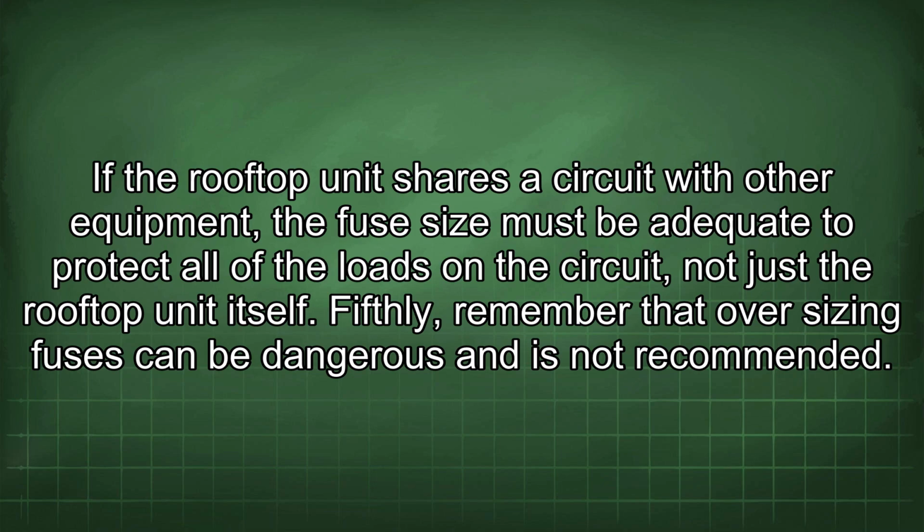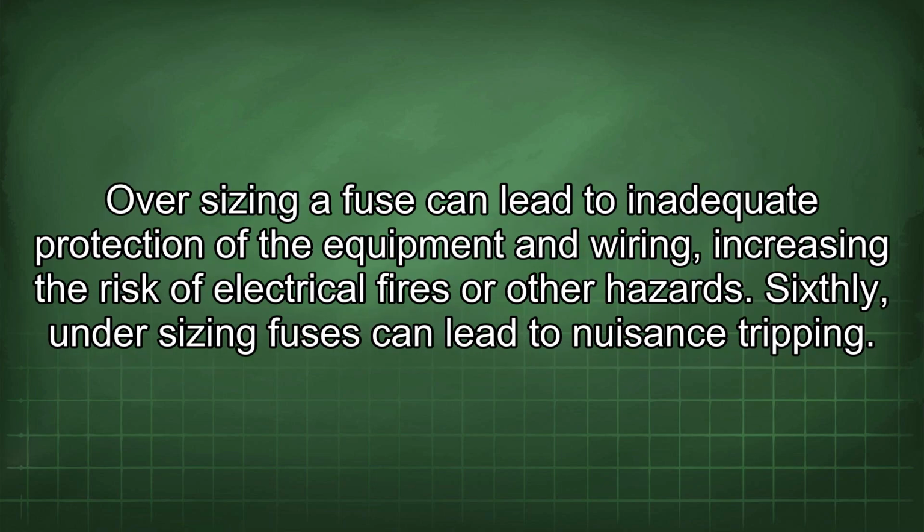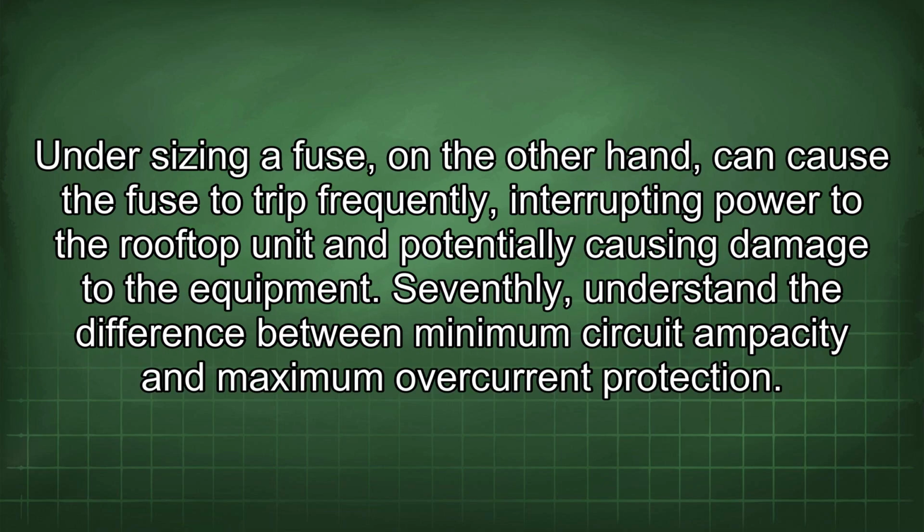Fifthly, remember that oversizing fuses can be dangerous and is not recommended. Oversizing a fuse can lead to inadequate protection of the equipment and wiring, increasing the risk of electrical fires or other hazards. Sixthly, undersizing fuses can lead to nuisance tripping. Undersizing a fuse, on the other hand, can cause the fuse to trip frequently, interrupting power to the rooftop unit and potentially causing damage to the equipment.